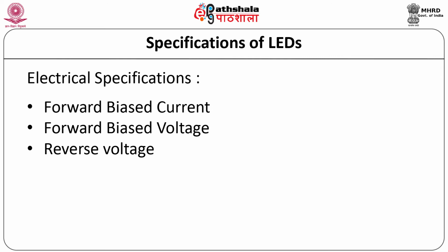If they are, then permanent destruction of the device will almost certainly result. If there is any chance of a reverse voltage appearing across the LED, then it is always best to build protection into the circuitry to prevent this. Normally, simple diode circuits can be introduced and these will adequately protect any LED.